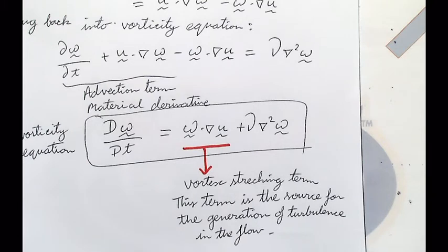No, why? If you have 2D flow, you still have kinetic energy in the flow, which you can decompose using whatever method you want: principal component analysis, POD, DMD, whatever you want, right? So there's still energy in the flow. The only thing missing is this inviscid cascade of energy, which is a very specific thing.